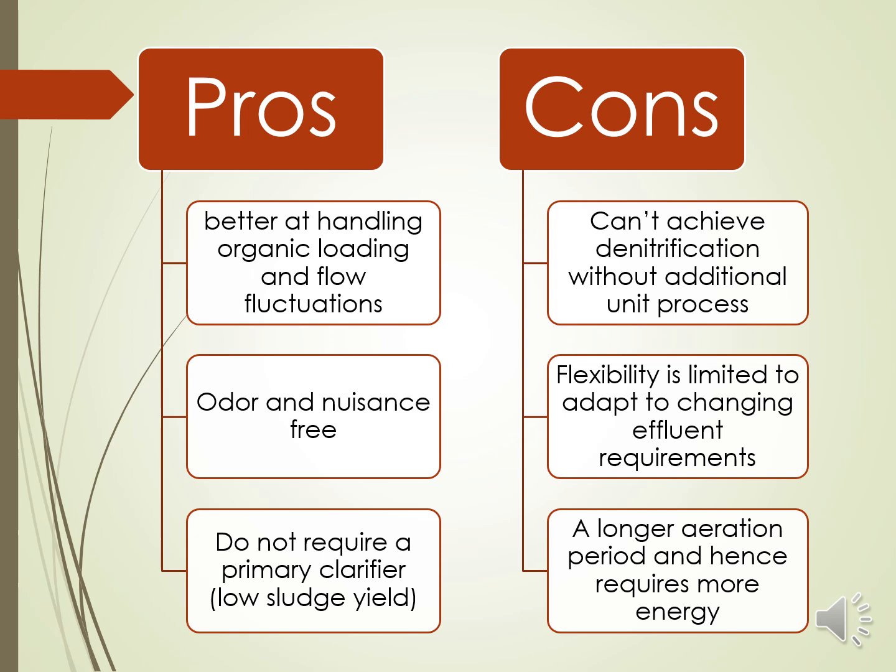For the long lasting or aged sludge, as we call it, the sludge becomes without odor. And finally, it does not require a primary clarifier, as I said before, because of the low sludge yield. Okay, low sludge yield. For the cons, first, we can't achieve denitrification without an additional unit process.